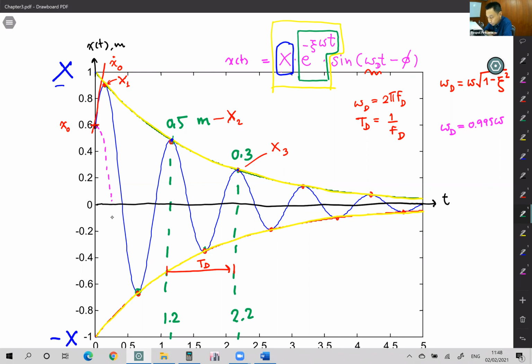But even though I use a reinforced concrete building, the damping ratio is still very low. It's only 2-3%, a very small number. That's why my building still keeps vibrating like this and takes more time to stop.